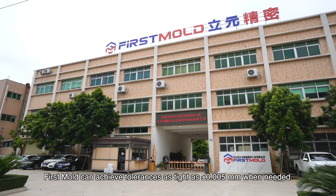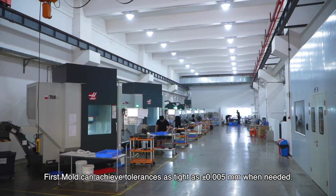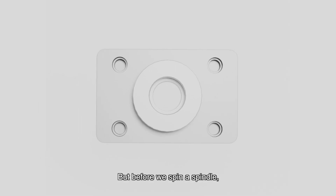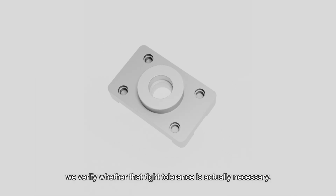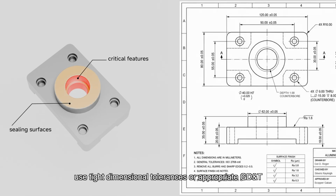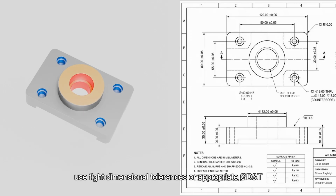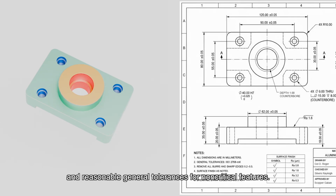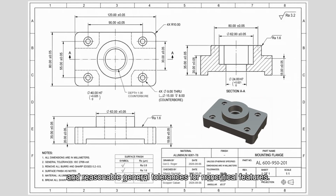First Mold can achieve tolerances as tight as plus or minus 0.005 millimeters when needed. But before we spin a spindle, we verify whether that tight tolerance is actually necessary. Our rule is simple. Use tight dimensional tolerances or appropriate GD&T for critical features such as bearing fits and sealing surfaces, and reasonable general tolerances for non-critical features.